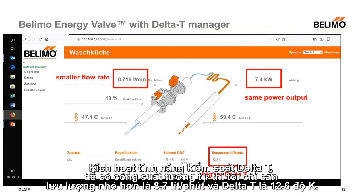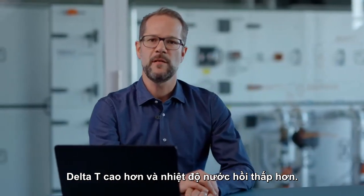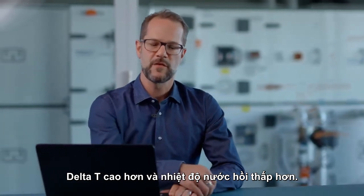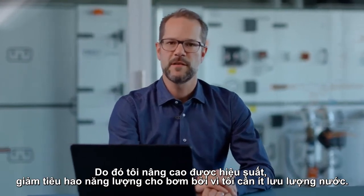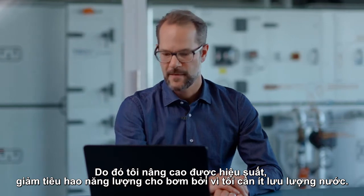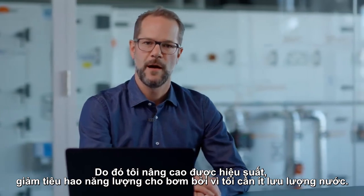Now I have the same power output, and with an installed and active delta T manager, I have here at the energy valve a much lower flow rate of 8.7 liters per minute and a much higher delta T of 12.6 Kelvin. So now I see with my condensing boiler the differential temperature is higher and the return temperature is lower, so therefore I have more efficiency on the condensing boiler and I need less energy on the pump side because I have a lower flow rate.